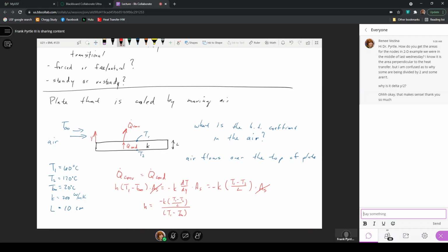So if I wanted to use this heat transfer coefficient as the average heat transfer coefficient across the surface, I could also calculate the temperature gradient in the fluid, and I'm already 1 minute over, so we'll stop right here. But the basic concept of the heat transfer by convection being related to the heat transfer by conduction in the surface is one that we've used before, but we'll extend this and consider that there is also a stationary set of molecules right across the top. So I could also consider how we would solve for the temperature gradient in the fluid right next to this solid surface.